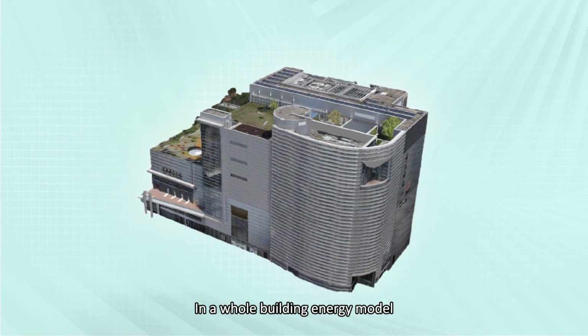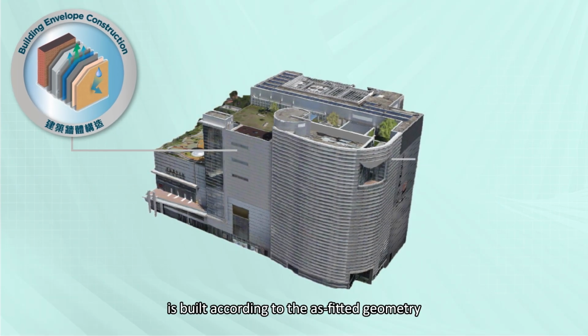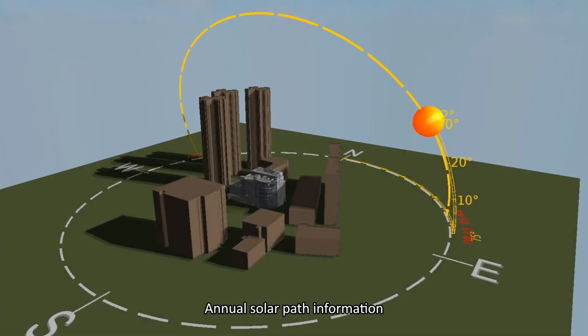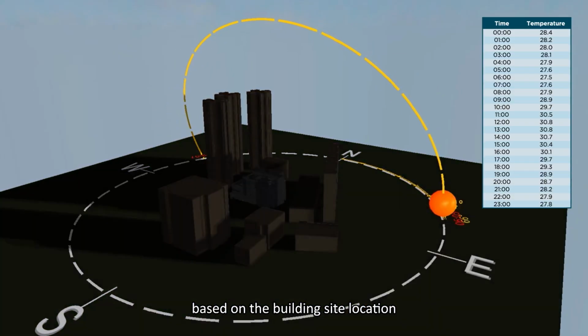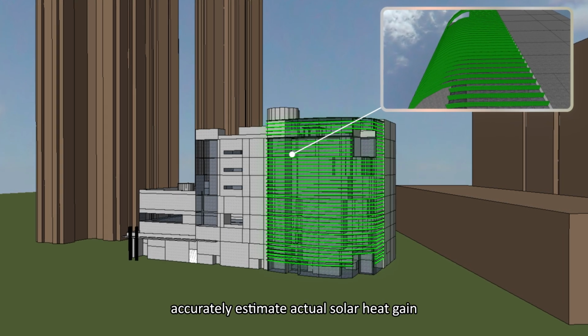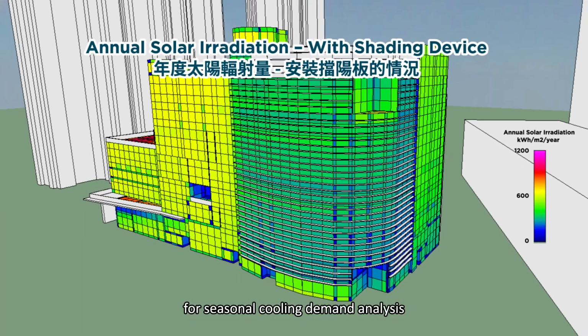In a whole building energy model, a three-dimensional model is built according to the as-fitted geometry and construction of the building to accurately represent the thermal properties of the building. Annual solar path information and hourly weather data are selected based on the building site location. Architectural features and shading devices are also included to accurately estimate actual solar heat gain for seasonal cooling demand analysis.